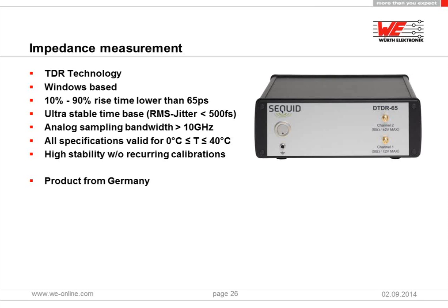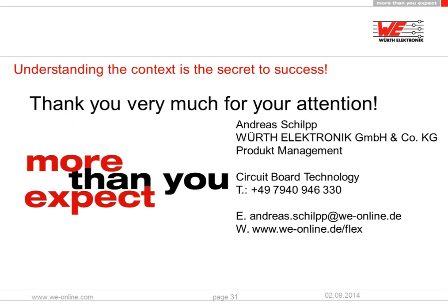So there are different aspects regarding this question. Regarding the signal behavior, as the signal is really fast, I think the signal will not see a difference whether we have an immediate change in the width or if we have a smooth transition. But regarding the aspect of the production, I would rather recommend to have a smooth transition, and also this helps to have a better feeling at the end. So the answer is, please use a smooth transition. The signal will not care about that.